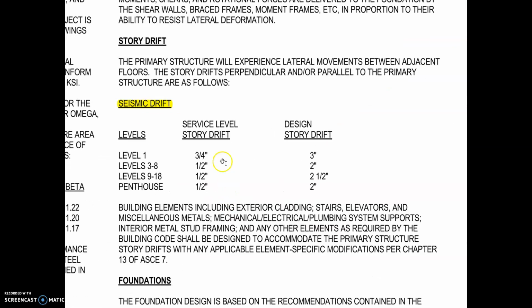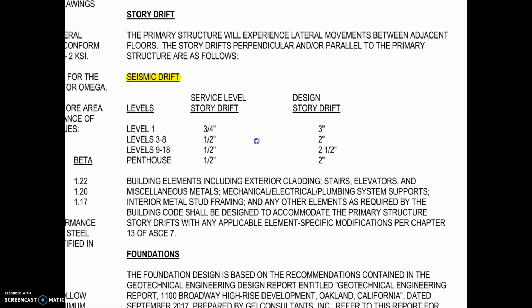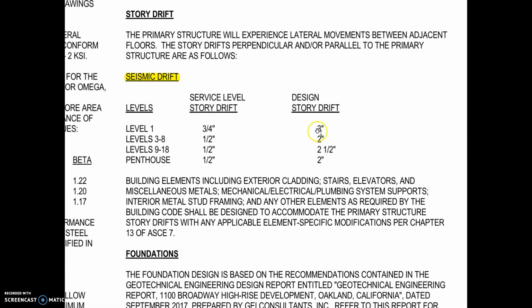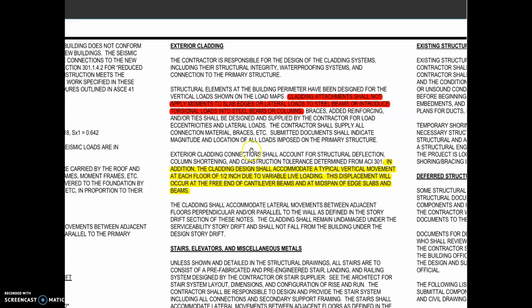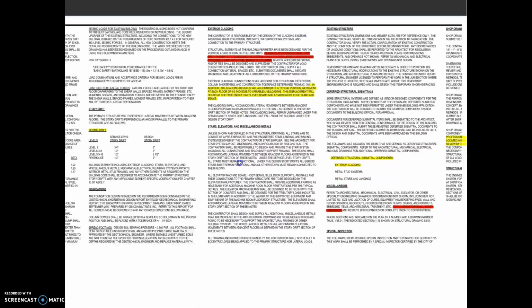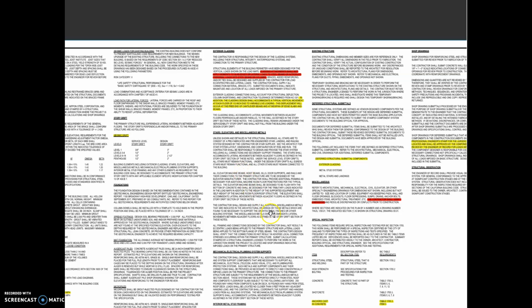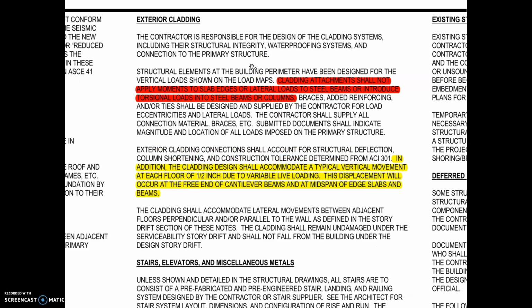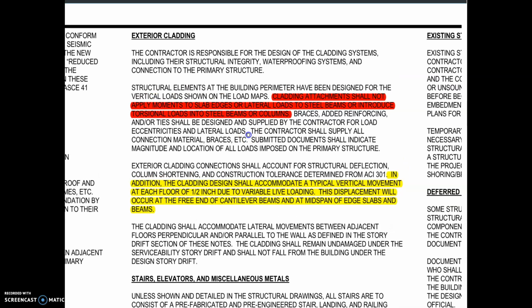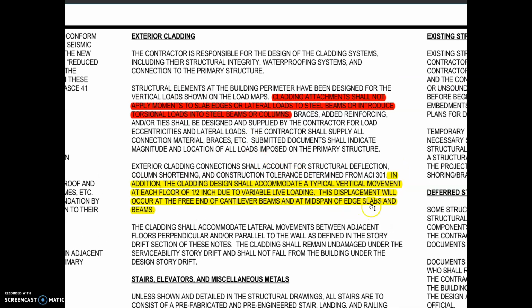And then up here, we have our seismic drift. So instead of giving us drift as a percentage, they gave us the actual drift worked out in inches based on the floor heights. And so here we can see our elastic drift and our inelastic drift right here. So then that's really primarily the main things we're looking for. And so then anything after that is going to be job specific. Any special notes that catch our eye that we want to be aware of.